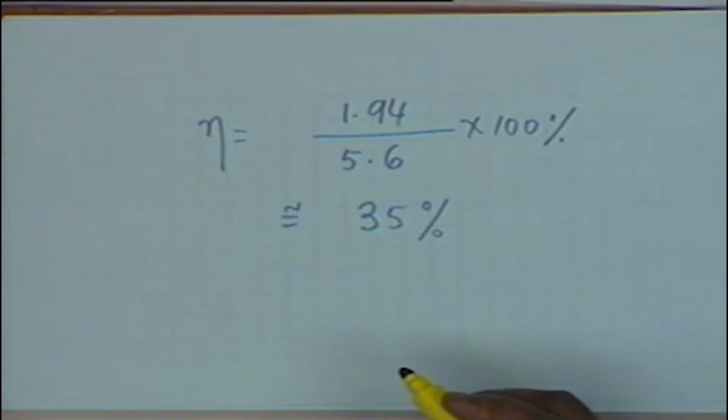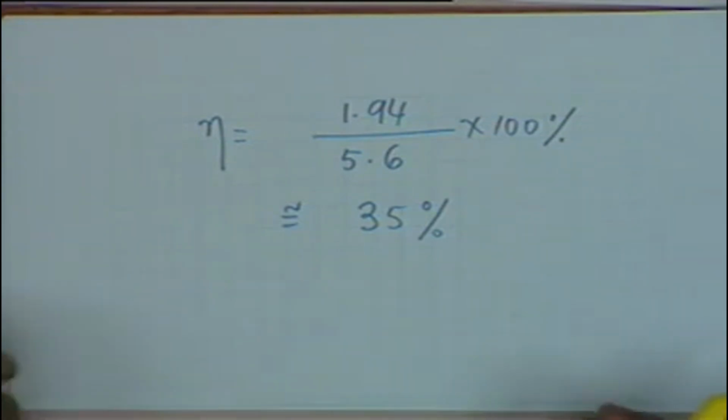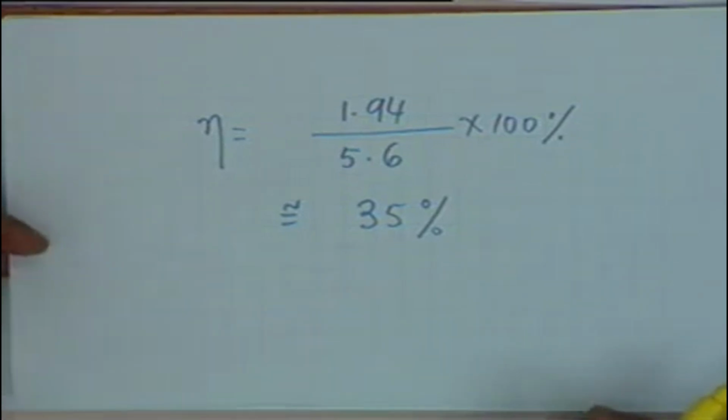The theoretical maximum is 50%, what we can achieve is approximately 35%, and this is a fact of life. All right. The design has to be very carefully done by looking at the transistor characteristics. For power amplifiers, transistor characteristics are a must if you wish to keep the distortion to within reasonable limits.